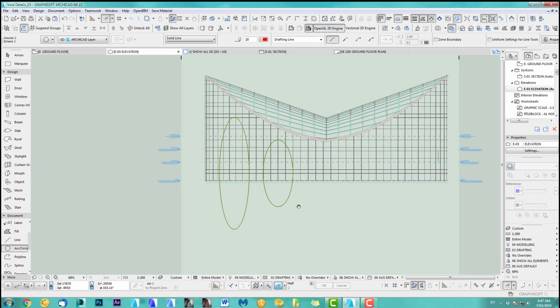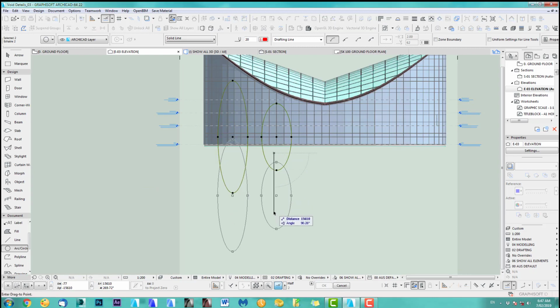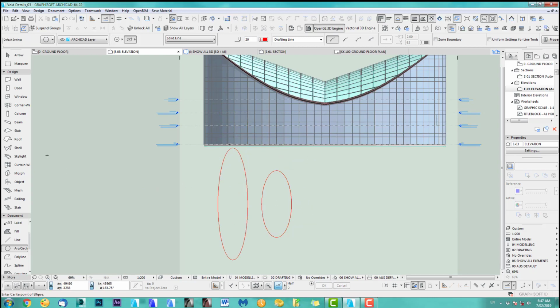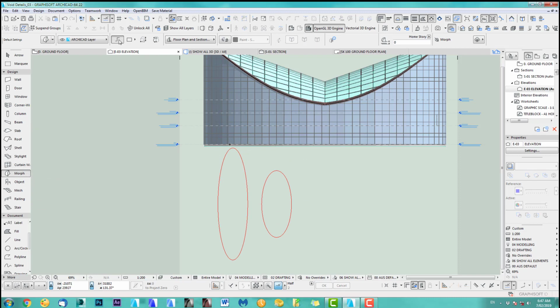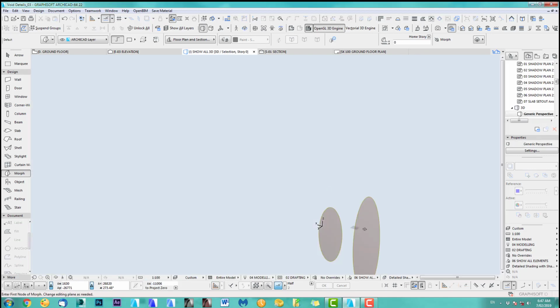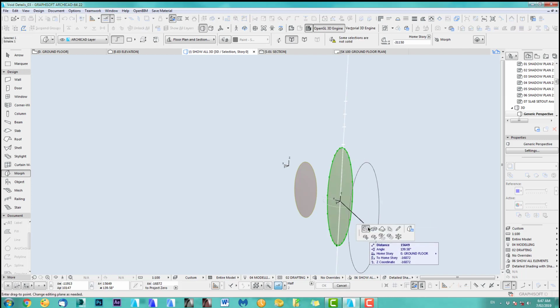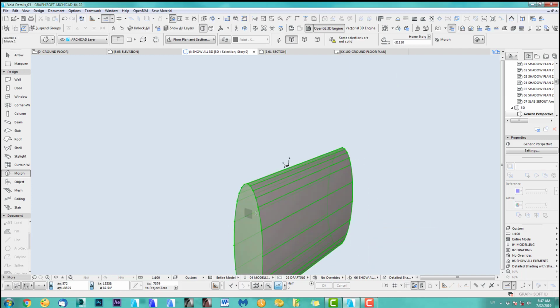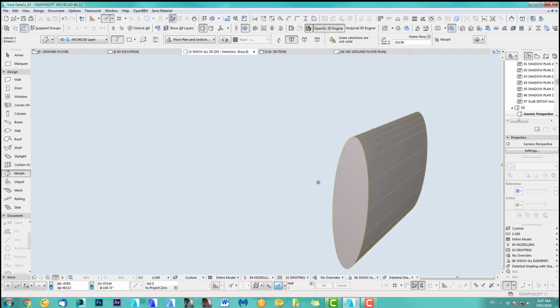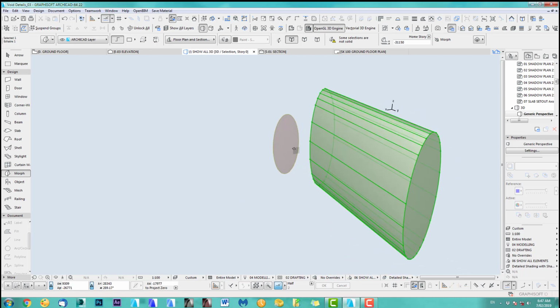So take those, drag them a bit down, but of course now I want to use the Morph tool, and we just draw two morphs. There we go. It's going to 3D, and we extend them a bit. There we go. You select and you just pull them out a bit. Okay, because they're all there, will just be used for cutting.